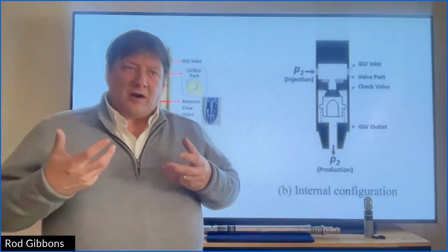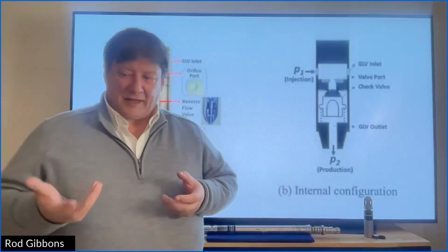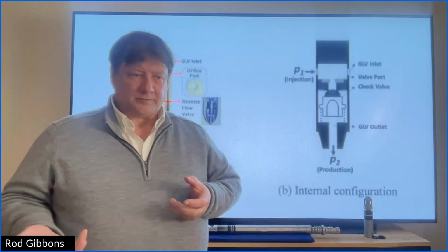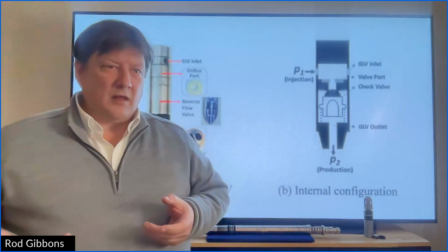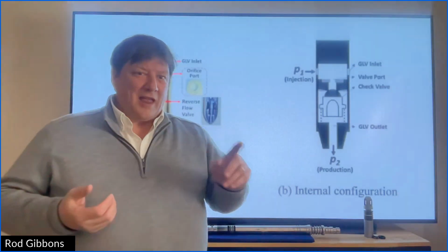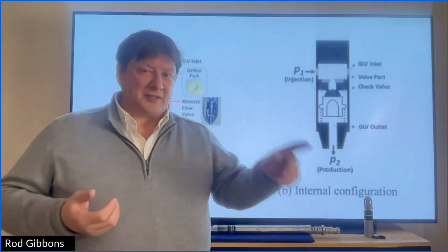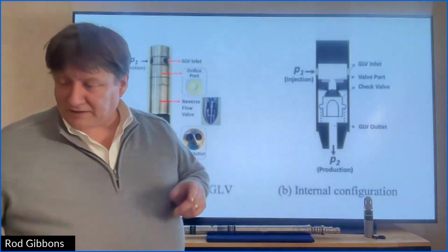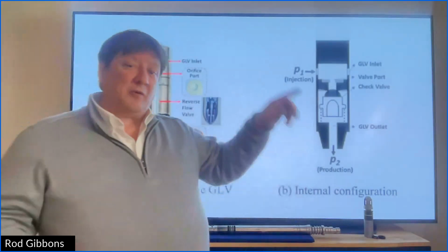So if you are compressing the gas because you need to re-inject it to conserve it, then you're really talking about the energy efficiency of recycling the gas through a gas lift system, because we'll put this gas through the well and then we'll produce it back out again.